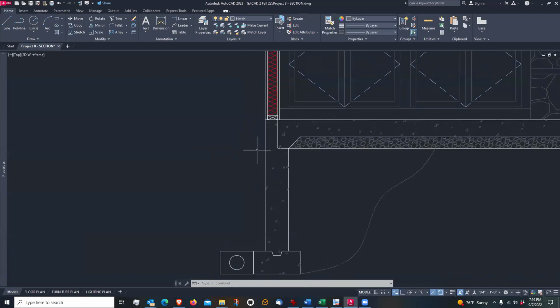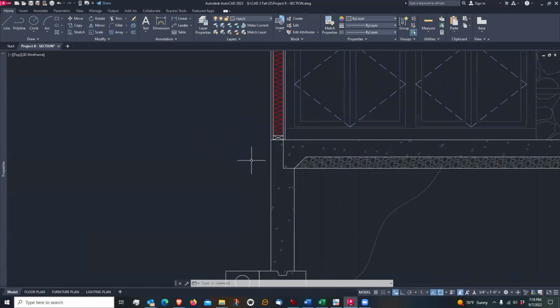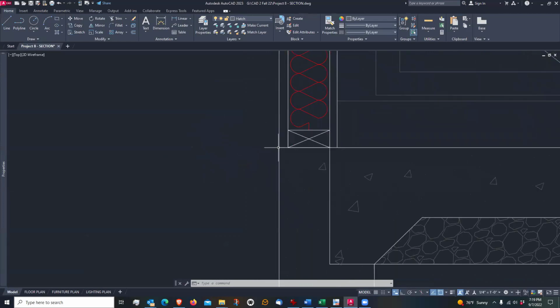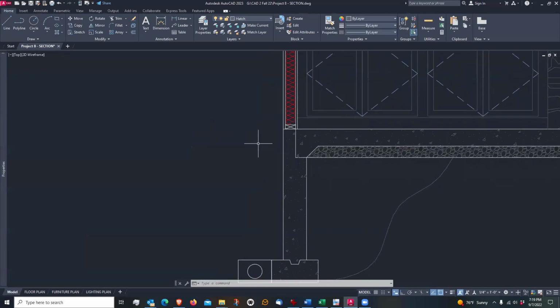So that if you're looking at the house, very often you will see concrete, and that's your foundation wall that you're seeing. It's extending all the way down 4.5 feet below grade. It's one of the reasons why sometimes we put bushes in front of houses, because we don't want to see that concrete. But we don't want our grade to be right here at our wall. We want it to be well below, in this case, if I look at my handout, by a foot.